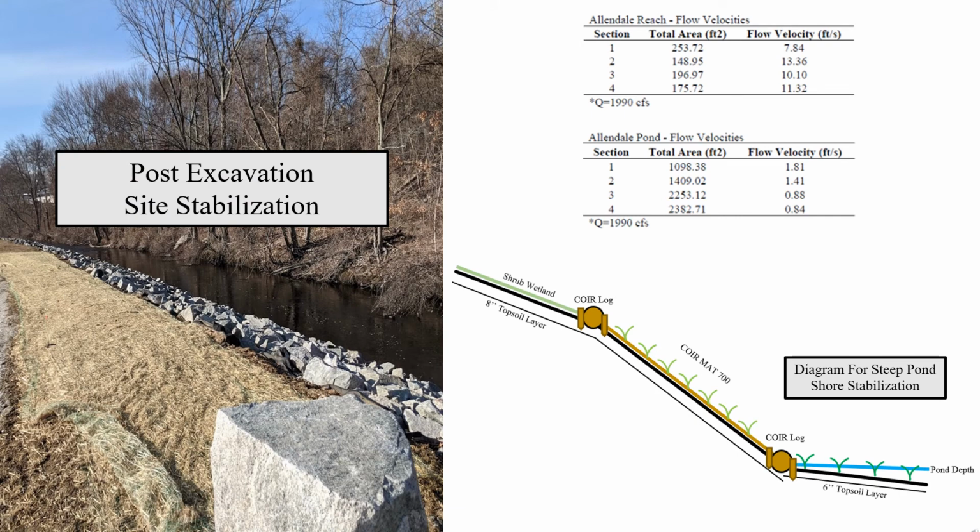The velocity of flow for the 100-year storm is important as it determines what type of stabilizing material can be used for erosion control, based on that material's velocity threshold. For the reach, the values for flow velocities were found by dividing the 100-year storm flow rate with the cross-sectional area. Because the calculated velocity for the reach is relatively high, the best material choice is 6 to 12-inch cobble riprap. The high amount of impermeable pavement in the adjacent area and the high disturbance to the environment through the dredging process necessitates the need for erosion control.